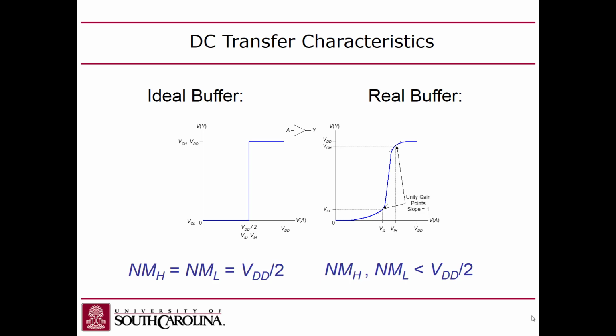So the idea is that you can raise the input with very little effect on the output, right, until you reach a certain point. Generally speaking, this is around 700 millivolts or so. We're on the threshold of the transistor, or around the threshold of the N transistor.